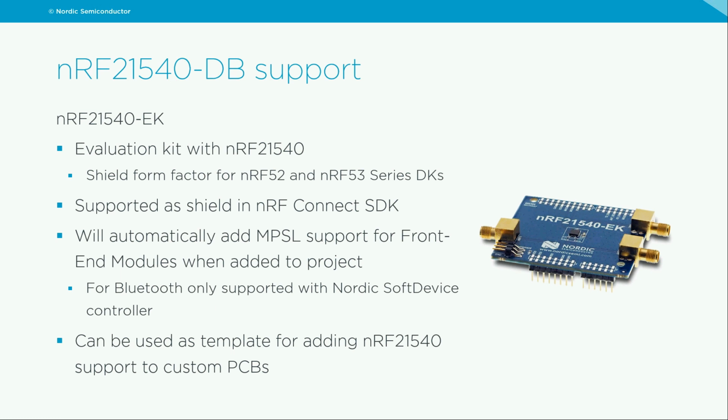And you can also use this as a template for adding nRF21540 support to your custom PCBs, because you will be able to see the overlay files that come with the shield, what features need to be in the project, and what descriptions need to be added to make it work.